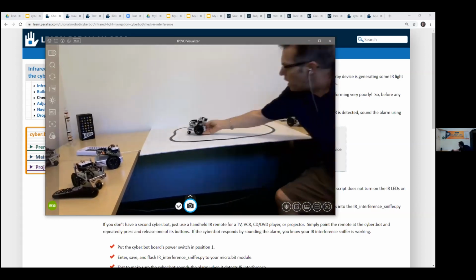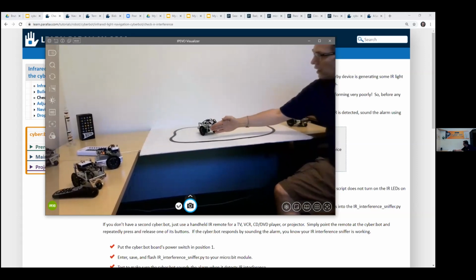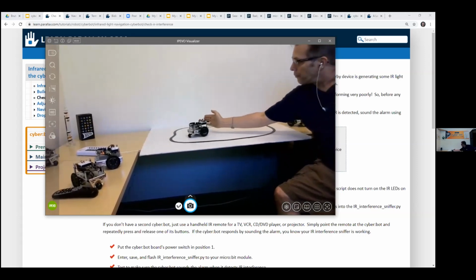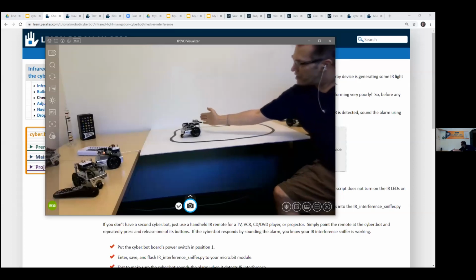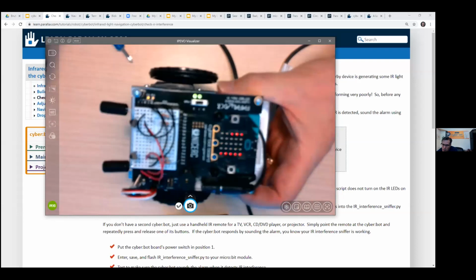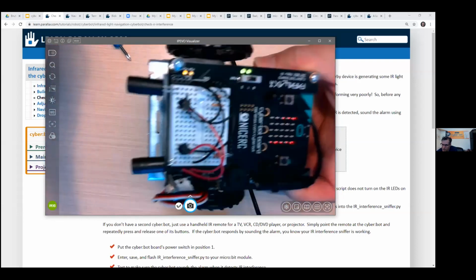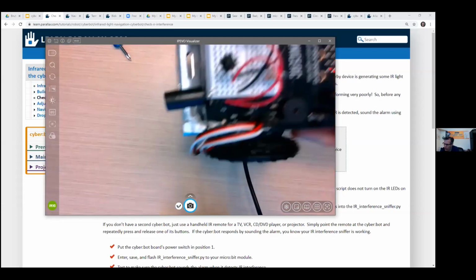Now, just by using a different program, you can instead demonstrate your ability with the force. And this is the robot you're looking for, I guess. Notice that what the script is doing is using the same sensors to measure the distance of the obstacle it detects, and it's adjusting the motor speed to try to maintain a constant distance for both sensors. And a quick close-up of that. Do you see how as I get closer, there are fewer lights on the microbits, and as I get further away, there are more lights?